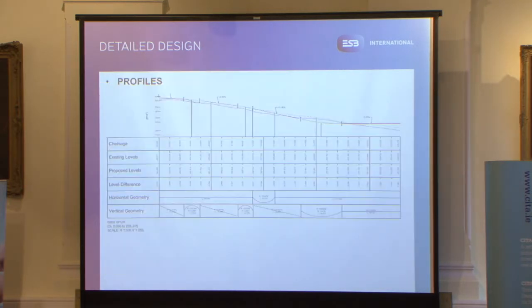Once this is established, we create a profile, through which we can create our design profile, which will also incorporate turbine supplier requirements for vertical alignments. We can then lock the profile to the alignment, which means that further down the line, if any modifications are required to the alignments, the level data associated with that particular location on the alignment is fixed and will not be altered.